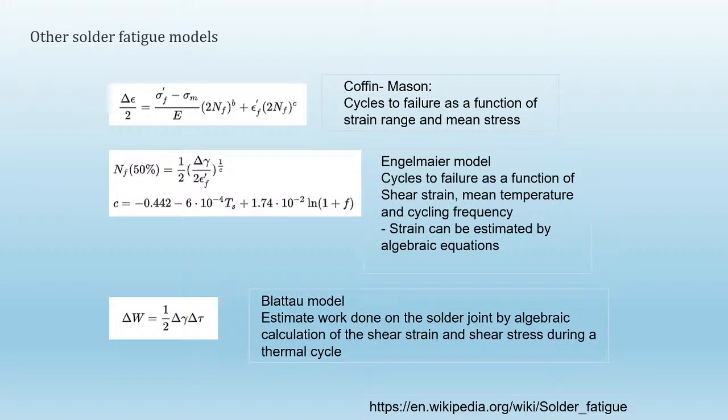Sherlock also has a whole host of capabilities on vibrational durability analysis, which requires a lot of simulation. Right? So on the thermal solder joint fatigue side, Sherlock's method, I think, for evaluating large board is great. It's very fast and allows you to get good estimates on simple packages. Sherlock has a whole set of capability on shock and vibration, which if you put any electronics in moving systems, vehicles, cars, airplanes, rockets, you definitely want to do those type of analysis. And they have a very finite element simulation based treatment for that.